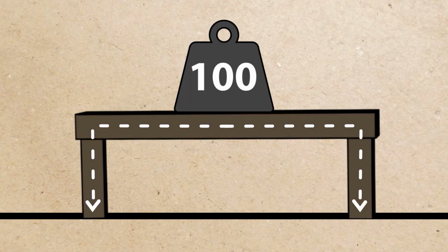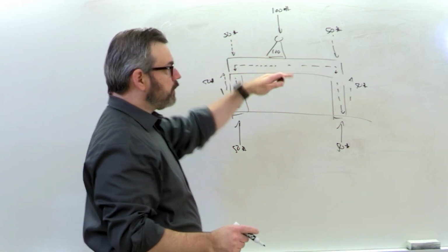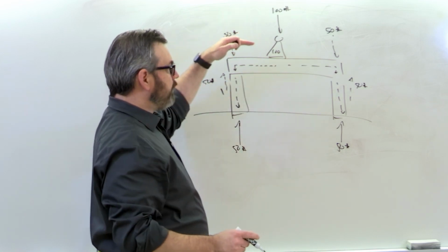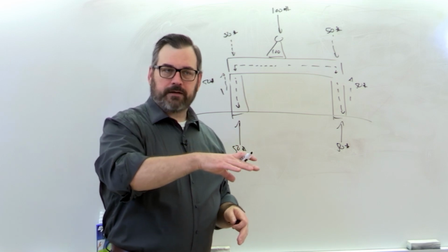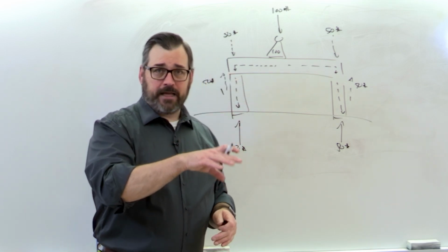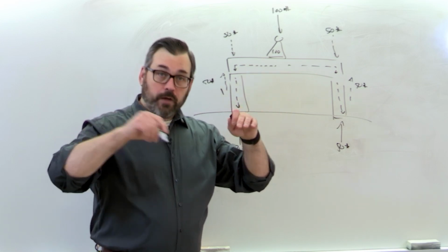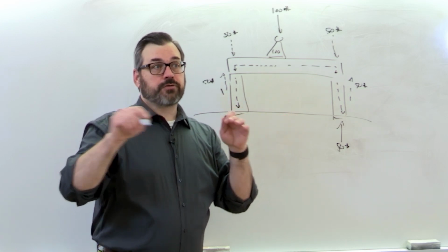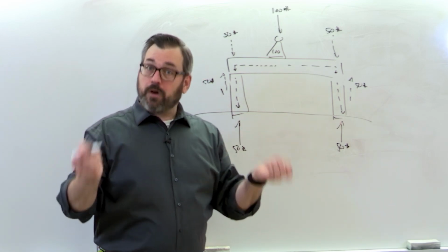When our structures get more complex, when it's not just a beam and two columns, we might have a series of beams and a plywood sheet on top of it. That plywood sheet is going to act like a beam and transfer load to each of the other beams, which are then going to transfer the load to legs or to another beam that supports those.